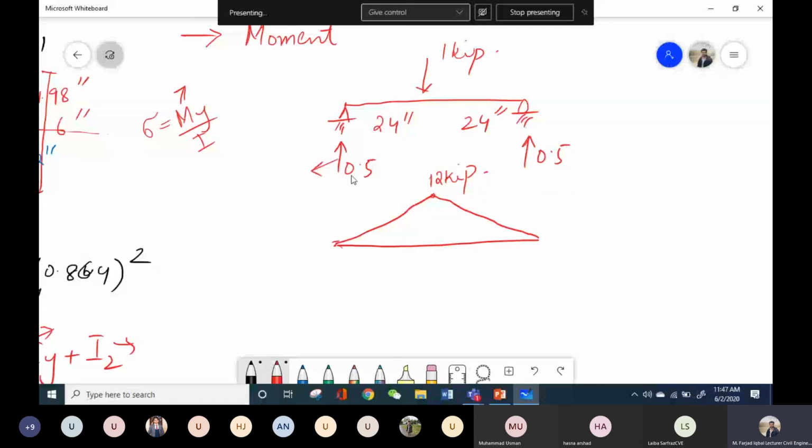So this bending moment is being produced in the clockwise direction. So what will be the resistive bending moment? It will be counterclockwise, and we have developed one sign convention that if the resistive bending moment is in the counterclockwise direction, it will be pointed in the outward direction in the section.